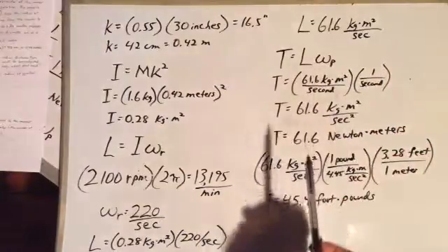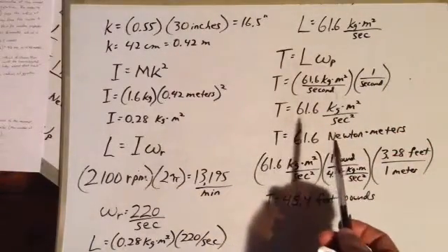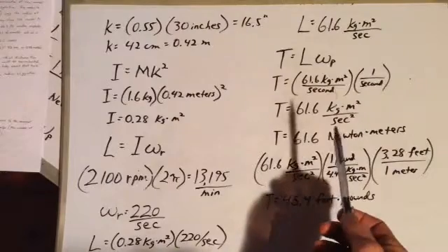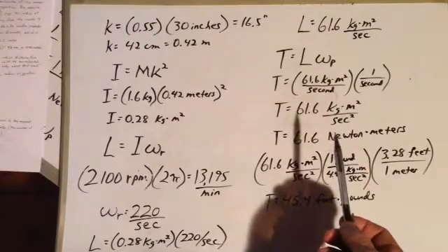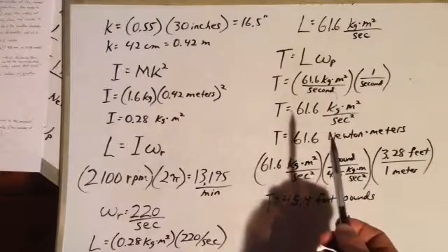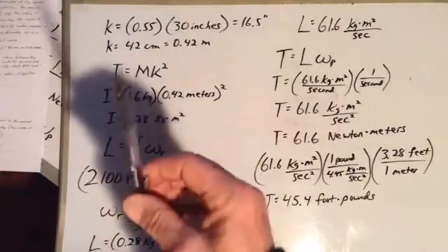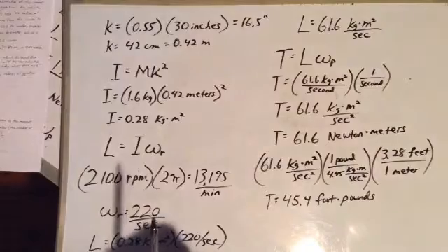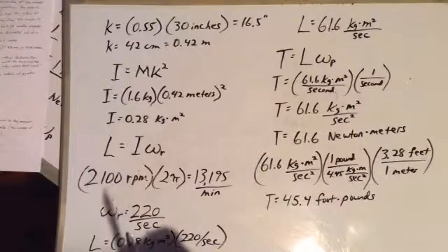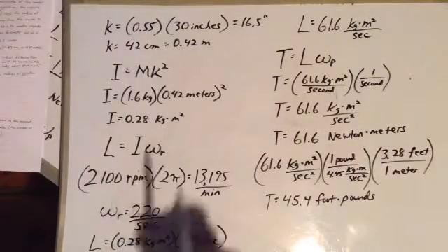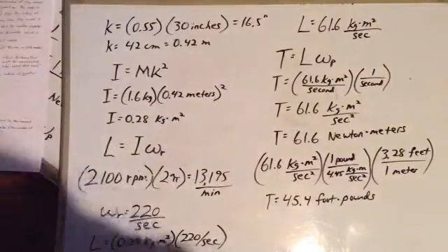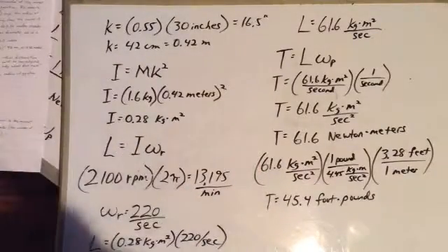Now we can talk about our power on stall. If the propeller is spinning at 2100 RPM during a power on stall and the nose of the airplane plummets 1 radian or 57 degrees in 1 second, then that 1 radian per second would be our precession rate.